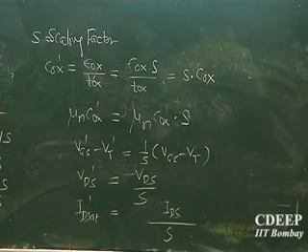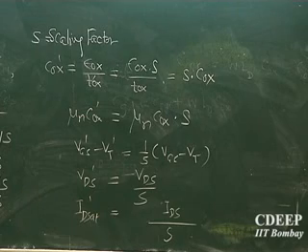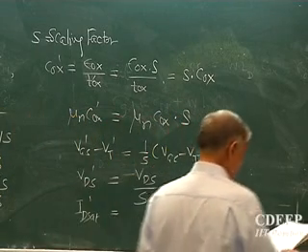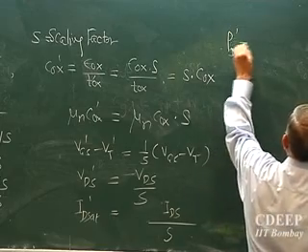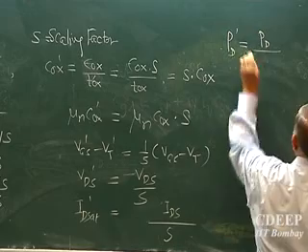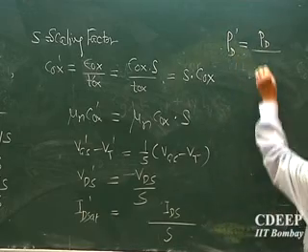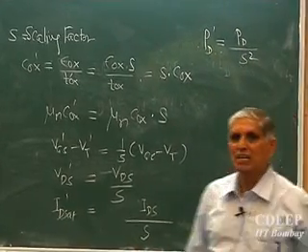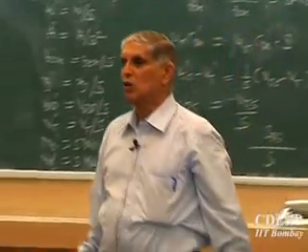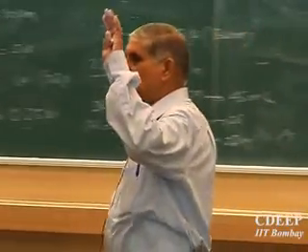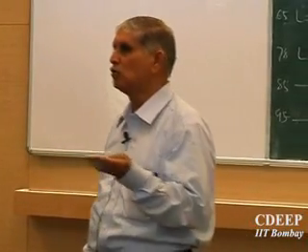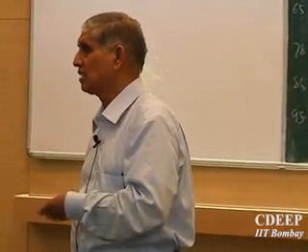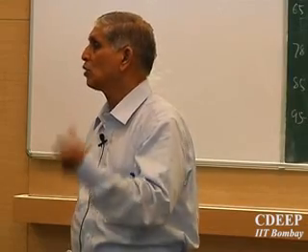Is that correct? So what will be the power reduction if VDD also scales and current also scales? The new power dissipation is the old power dissipation by S square. So what is the advantage I got? Low power. I reduced the power by scaling. I scaled the device, the power dissipation went down by S square. Is that correct? That's something I was looking for.